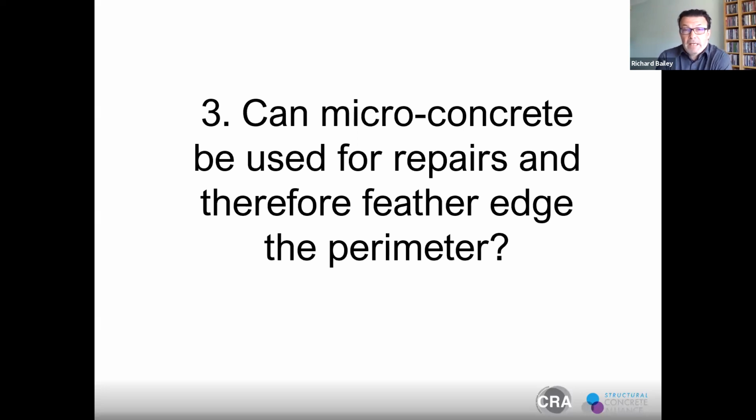And BS EN 1504 requires us to work to a well prepared edge. And this might be achieved through using a percussive or pneumatic breaker, but whether it's saw cutting or a pneumatic breaker, in both cases you're generally holding a tool in a hand, and that's something I'm sure we're going to cover a little bit more. But we want to get rid of that situation and take the tools out of people's hands.